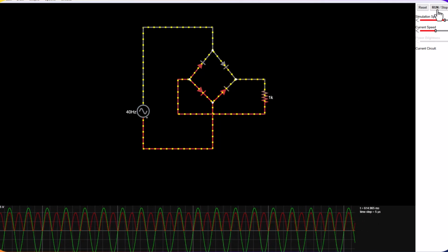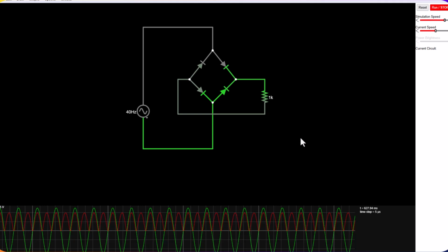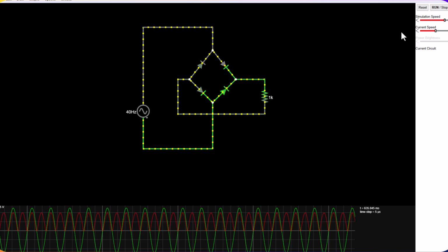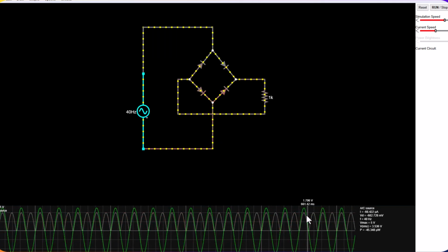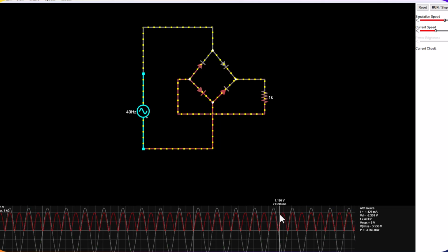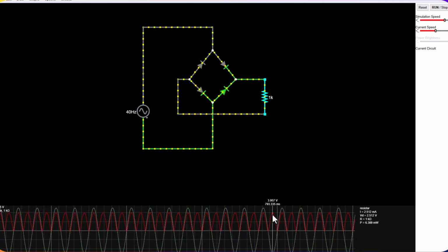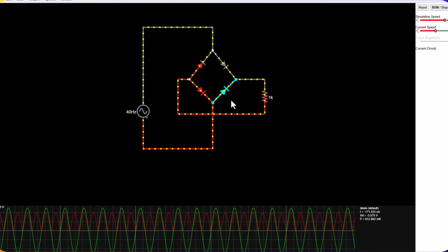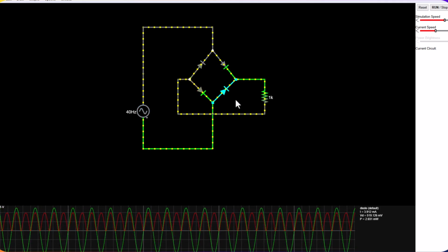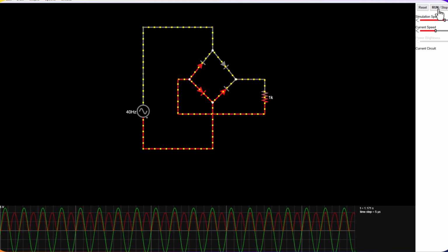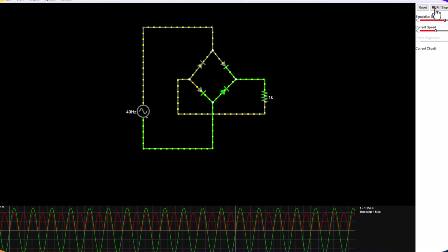You can see positive as well as the negative half of the input waveform are rectified in this rectification. Here we can see there is also a slight decrease in the output waveform. The size of the amplitude is decreased here. This happens due to the potential barrier of each diode which are contributing in the circuit. Now we'll go back to the PPT.